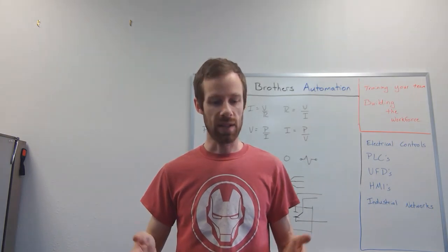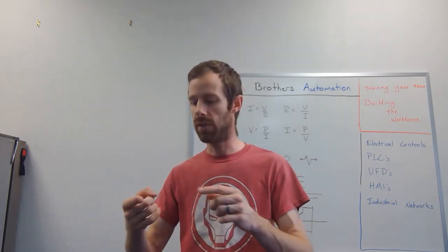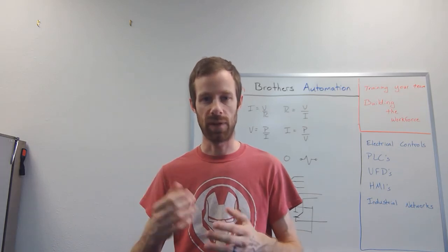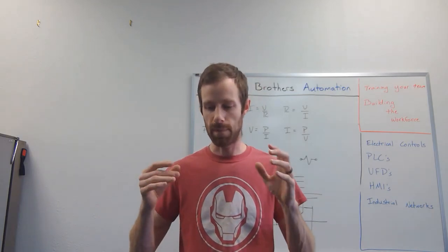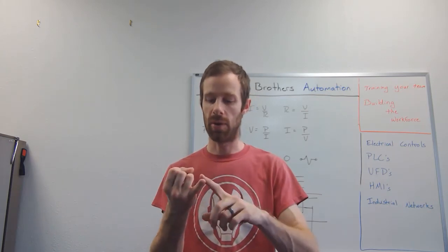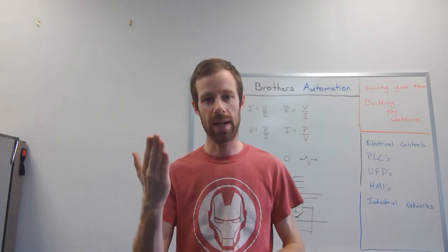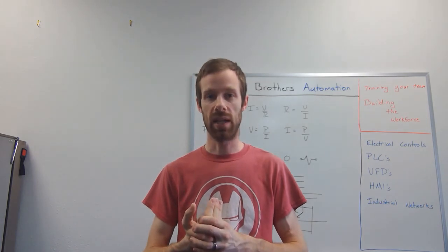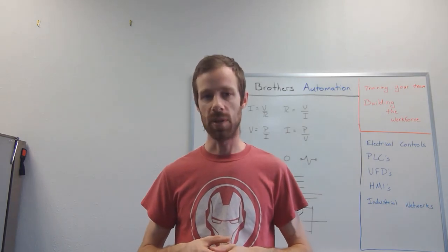because you can have a project that has 1,000 wires in it, and if you just bring it back to a simple path of electricity from a power supply through the conductors to the load, including any control devices, you can verify the first circuit. Then you can verify the second, and then the third, and then the fourth. And instead of thinking about this massive assembly as hundreds and thousands of wires, you think about it as little tiny sections of a power supply, conductors, the load device, and any appropriate control devices, and bring it back to the simple stuff. Electronics is complicated. I'm not saying that it's simple, I'm just saying that if we overcomplicate it, it's going to be terrible. So let's not overcomplicate it, let's keep it simple.